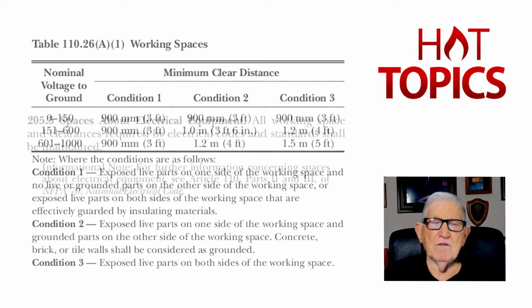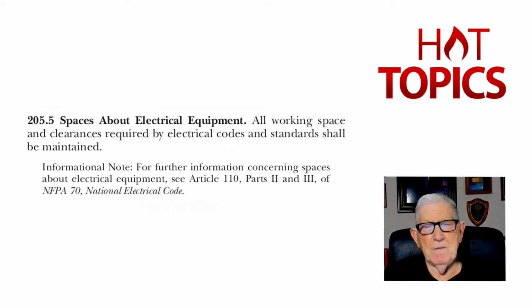And 205.5 of 70E on page 42 references the user of 70E to the NEC 110.26 for work clearances. And those clearances are in line with OSHA 1910.302 through 1910.308, when everything's totally enclosed. There's no opening at 50 volts or more that you could get into and get shocked in some way by touching an energized component, part, conductor, etc.